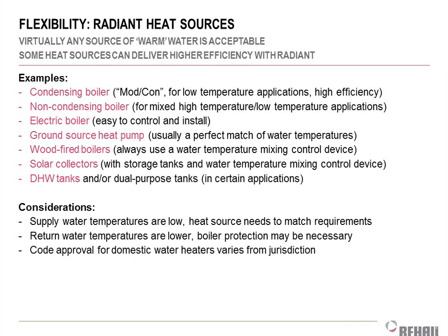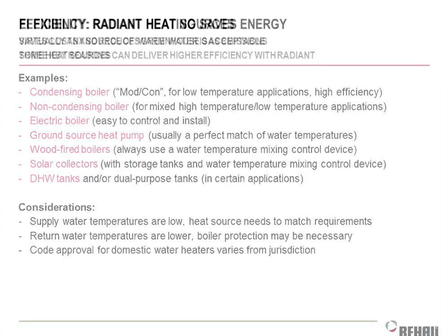Right? So I don't need very hot water to do this. Low supply water temperatures are suitable for radiant floor, so that means my water source can be a much wider range of things than a normal building might allow.